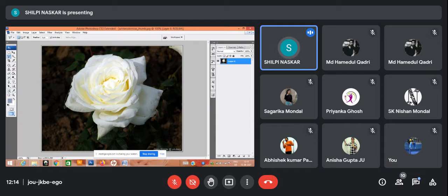I'm just clicking on the edges where I need the selection. This creates a polygon shape basically. I'm not selecting properly, I'm selecting abruptly, but it creates a polygon shape for the selection. You have to go back to the origin. See, on the right side of the polygon tool, there is a small o marked, which is the origin. If you click on it, the selection will come.